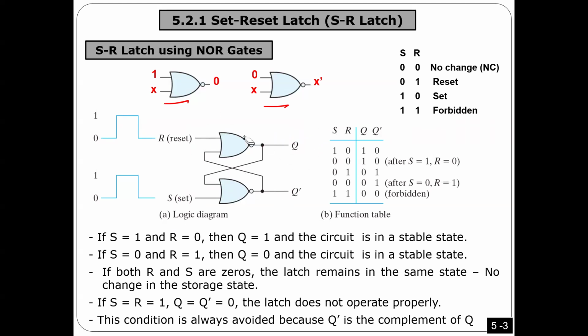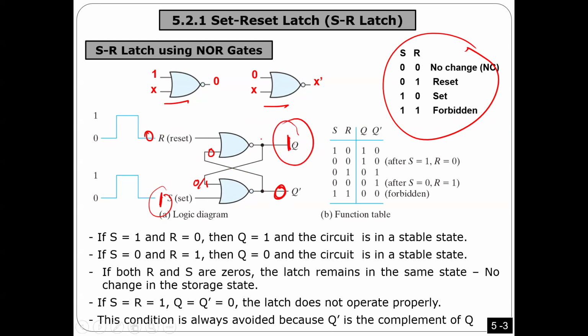Also, I promised, if we make this from this table here, if I make this 1 and I make this one 0, I have to make set. Let's see how. This one is 1, so this one is 0, regardless of whatever I have here. So if you have here 0 or 1, it doesn't matter. Once this one is 1, I have here 0. And this 0 is going to come as feedback here. 0 and 0, so this one should be 1. And this is a stored value. So here, yes, if there is a 1 here, 0 here, I'm going to store 1. Make sense? Okay.